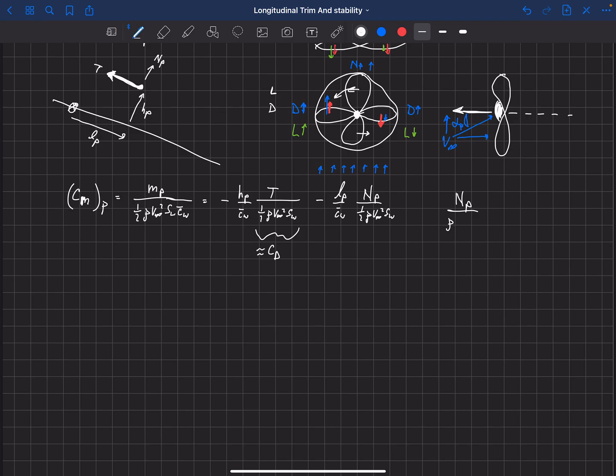When we non-dimensionalize propeller coefficients, we usually use rho times omega over 2 pi squared times the diameter of the propeller to the 4th. Okay, so that's how that's usually non-dimensionalized, and then we would call this a normal coefficient of the propeller.